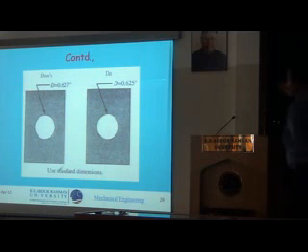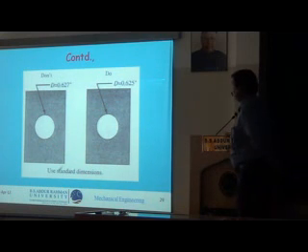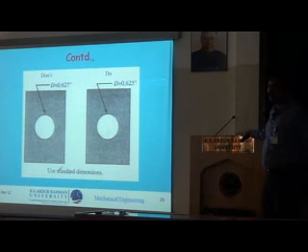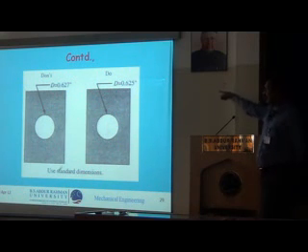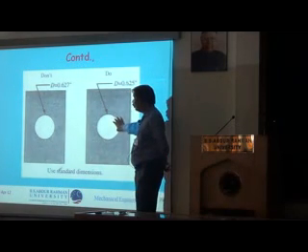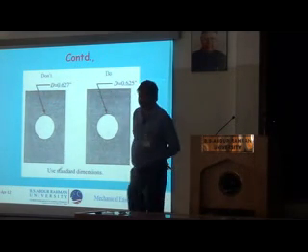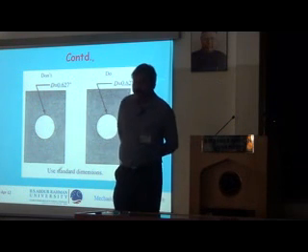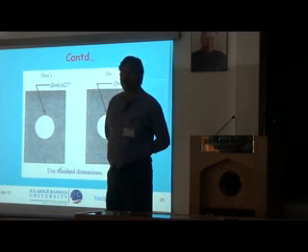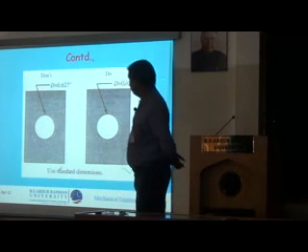So a 5/8 hole, 5/8 of an inch, is what is specified here. Generally we should follow millimeters only, but in machining we still do follow the British system, the English system also. So this is the 5/8 hole. That is a standard drill bit available. I can easily make this hole. If you say it is 0.627, I don't have a drill bit for that. I should go for a special manufacturing process like boring, which is expensive. Next.